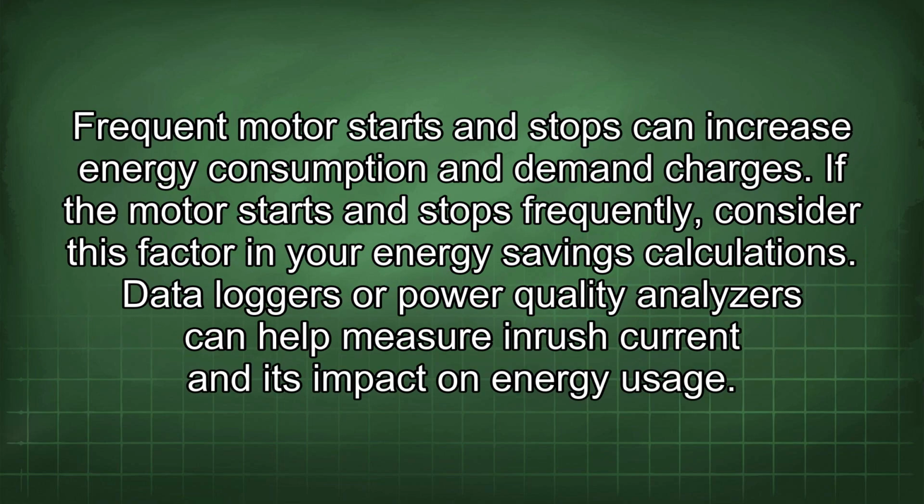Frequent motor starts and stops can increase energy consumption and demand charges. If the motor starts and stops frequently, consider this factor in your energy savings calculations. Data loggers or power quality analyzers can help measure inrush current and its impact on energy usage.